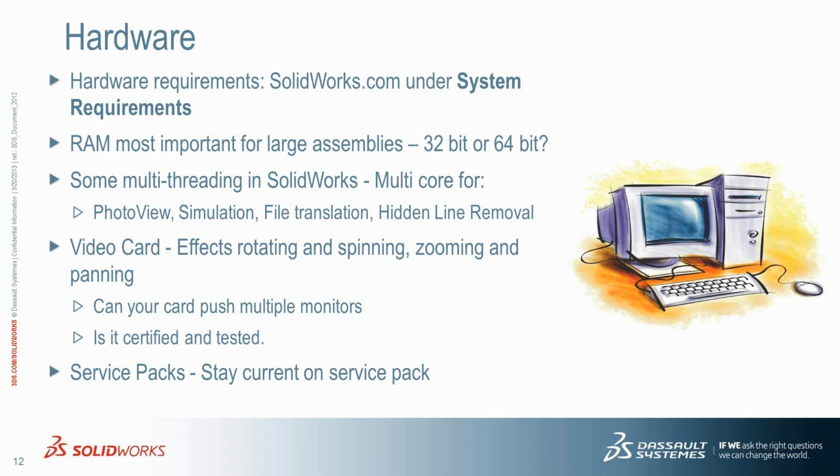And depending on the resolution, you may be pushing the memory on that video card as well. If you're pushing that, it might, again, affect your pan, zoom, and rotate speeds, and the quality of refresh rates on the screens themselves. If you're spanning screens, just make sure your card is going to be sufficient to handle that. And there will be some notes within the certification and testing and the video card page to help you with that.